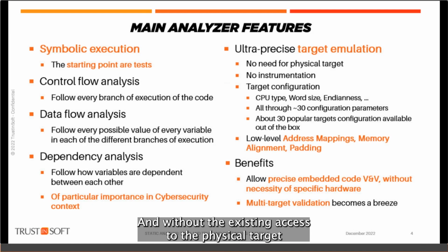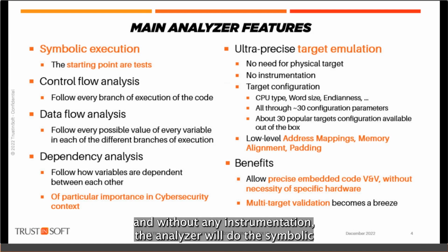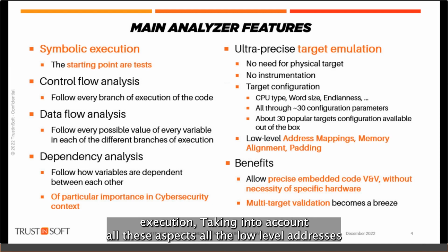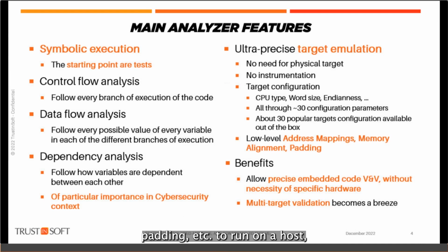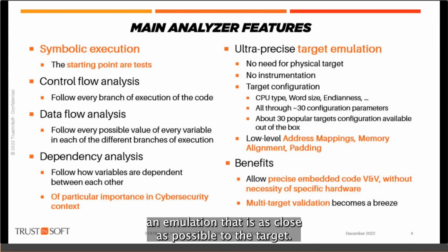And without access to the physical target and without any instrumentation, the analyzer will do this symbolic execution, taking into account all these aspects, all the low-level address mapping, the memory alignment rules on this target, the padding, etc., to run on the host an emulation that is as close as possible to the target.